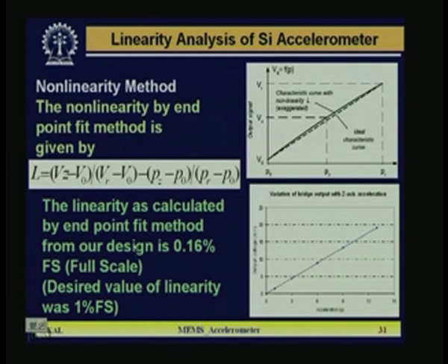For the linearity as calculated by the endpoint fit method from our design, our curve is this curve, the z axis acceleration plot from earlier, which has been repeated here: acceleration versus the output voltage. This curve's linearity was found to be 0.16% of the full scale. Our design target is 1% of the full scale, so we are getting far less than our expected value.